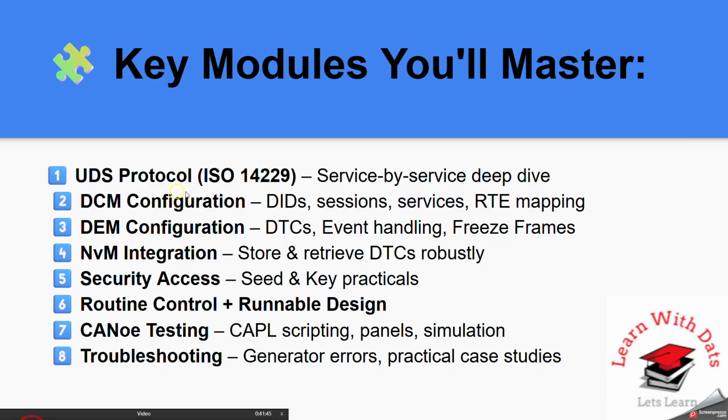NVM integration, how these diagnostic events or DIDs will be stored into the NVM, or if you want to send a request to read the data from the NVM, how it happens, everything is covered. What will access, how it will protect the data. Some practical examples are given.